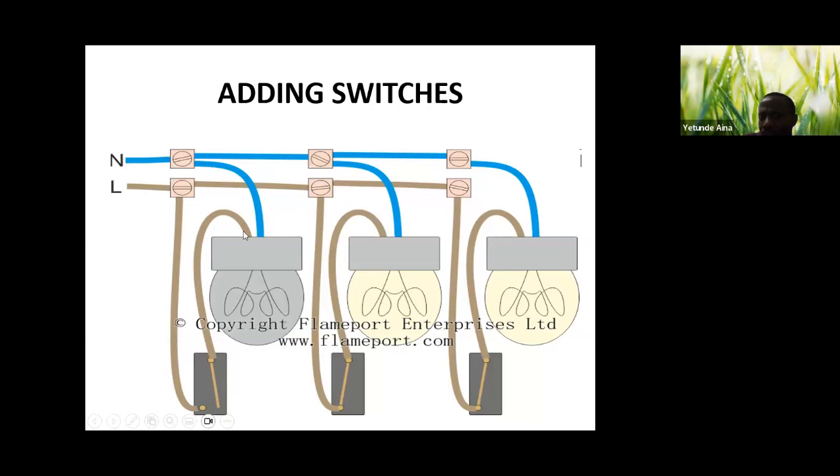Although in some connections you may see them using a blue wire for this one, it is not representing black in that switch. It is not representing black. It's the feedback to the bulb. Now look at the neutral. As far as the neutral is concerned, the neutral is connected directly to the bulb. Now the same thing is applicable here. We have the live coming directly here, and the feedback is connected to the bulb, while the neutrals just go like that, like that. The neutral also comes back to the bulb.